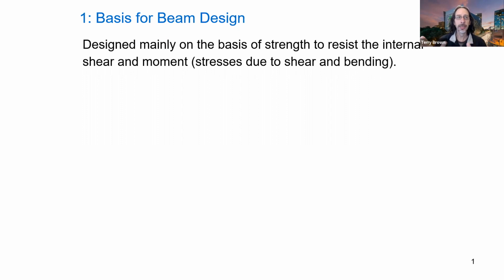All right, so usually when we're designing a beam or a beam-like structure to carry a load, we usually do that on the basis of strength. Okay, so we want to know that the beam is able to carry the internal shear and bending moments that are required by the loads that are placed on it.